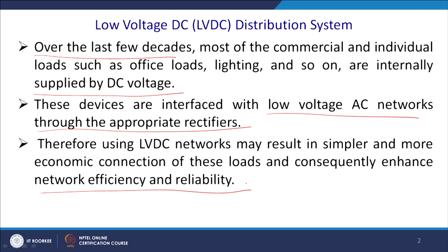Your cable power handling capability is required to be derated, your transformer is required to be derated. It may also cause interference with the communication network, as well as oscillations in the power system, because you may have a natural frequency of oscillation that is close to the 7th harmonic in most cases, because you mostly have a capacitor bank, and thus, with the leakage reactance of the big transformer, that gives you the natural frequency of oscillations.